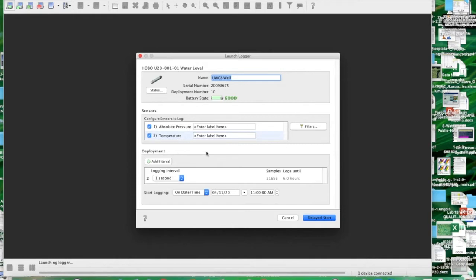And so in other years we went to Sunnyside Elementary, and I may be giving you those data, but Sunnyside Elementary has a very, very sandy aquifer, and it only takes about 3 or 4 minutes for the entire recovery to take place. The one on campus that I'm going to show you takes much longer. For the bail down test, the one well took something like 34 minutes and it wasn't completely recovered. The other well took over an hour and it still had 12% of the recovery left. So these are not quite as coarse, not quite as highly conductive sands.